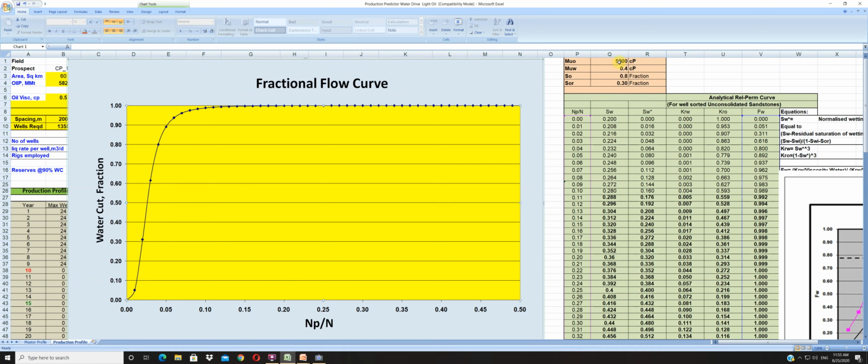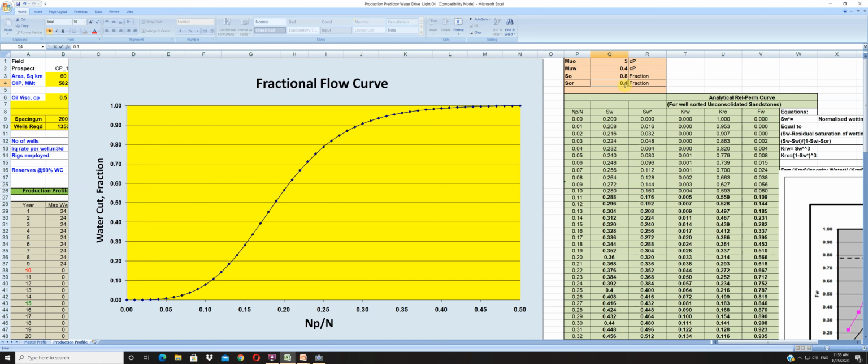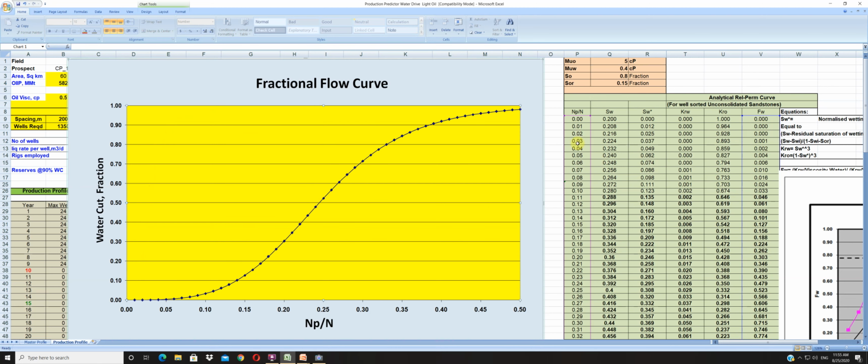See, many reservoirs all over the world are very popular with steam injection for this type of reservoirs, wherein viscosity goes down to a very low number and reduces the SOR to 15%, even lower, 10% or so. But for demonstration purposes, I'm showing just 15%. And you can see how a significant amount of oil in US, Canada, Venezuela, China, Russia is extremely popular with steam flooding, and for this type of oil the most successful EOR project has been steam in such reservoirs.